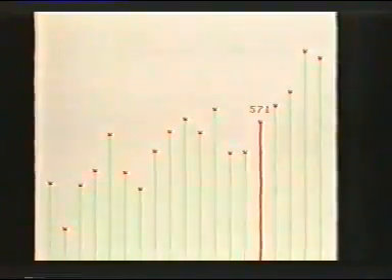So the accuracy of the representation of the analog input would be very dependent upon the size of the time slices. You can actually see it on that original graph. When I was moving it very slowly, it gets a fair representation of moving it. When I moved it very quickly, obviously I was moving it further in the time slice that was allowed. That's the major problem with analog devices. You must sample very frequently if you're to get an accurate representation. So 2 analog inputs there we've dealt with.